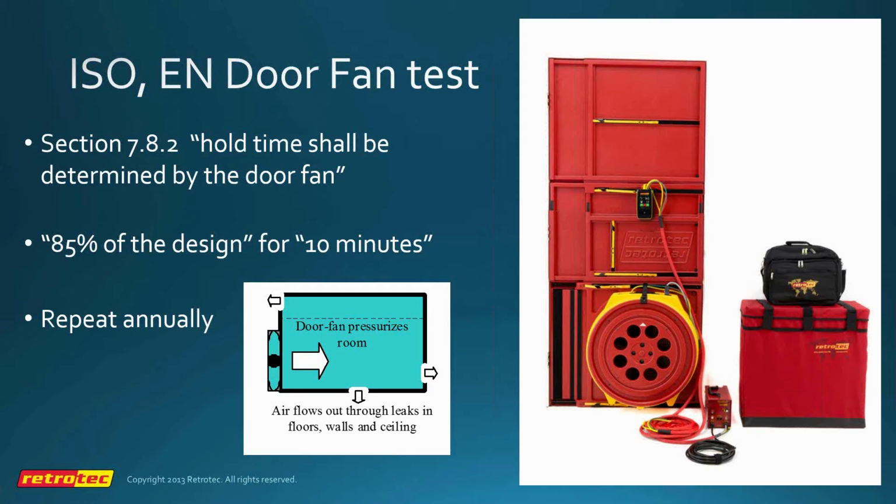Suffice it to say that everything that you have to do for ISO, you also have to do with NFPA. The fundamental difference is that ISO's philosophy is you cannot use enclosure leakage for venting, so typically they design them so you don't use them for venting. Whereas in NFPA, if we design the enclosure correctly, we can use enclosure leaks for venting. So that's the main difference.